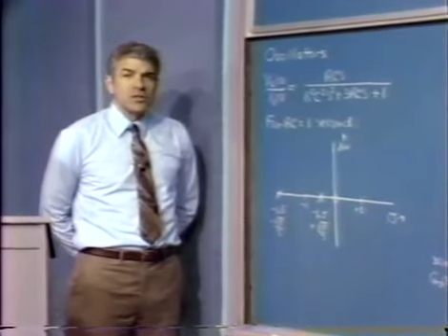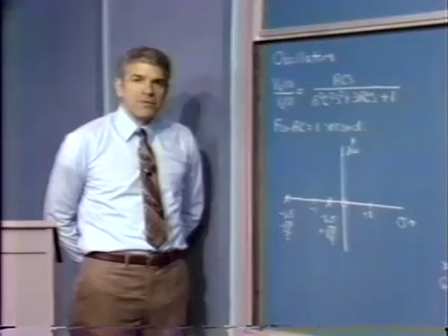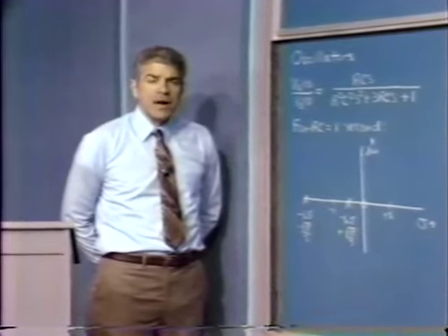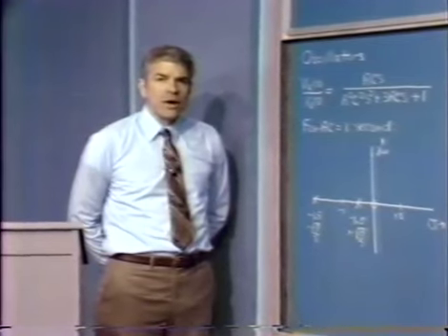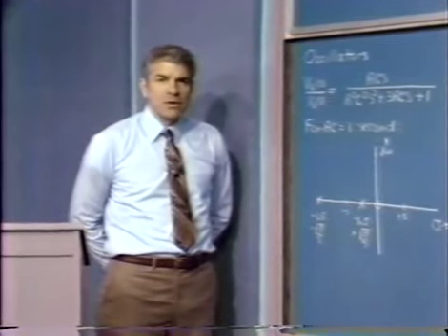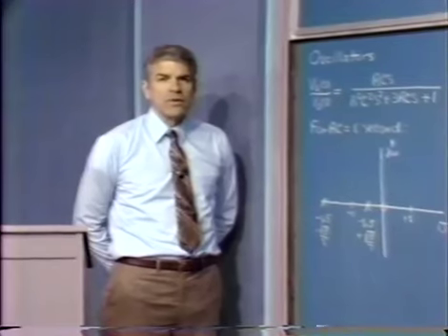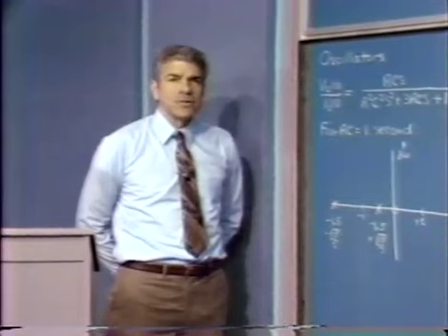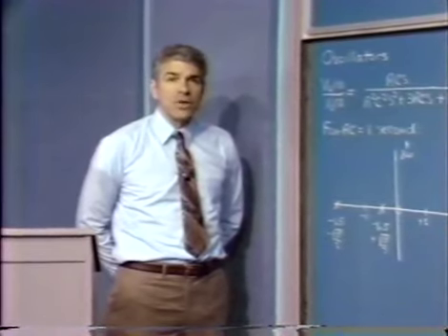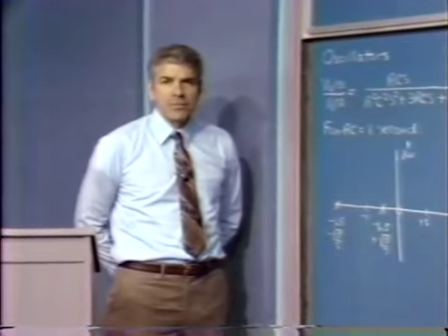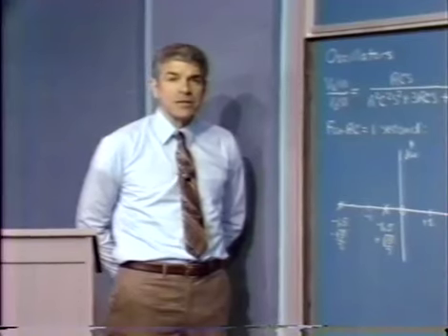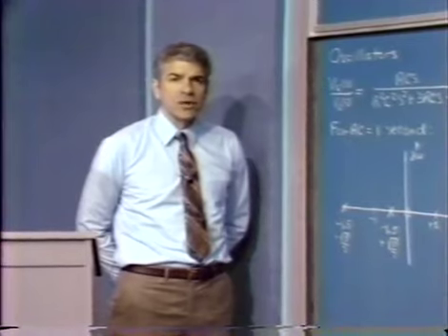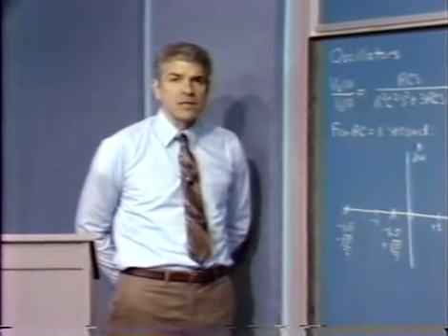Consequently, if we surround the Wienbridge with an amplifier with a gain of precisely 3, we can form a positive feedback loop where the loop transmission magnitude is precisely 1 at only one frequency, in particular at omega equals 1 over RC. At that frequency, the Wienbridge provides an attenuation of 1/3. The operational amplifier, as I showed in the view graph, provides a gain of 3, and so we have a loop transmission whose magnitude is precisely +1.